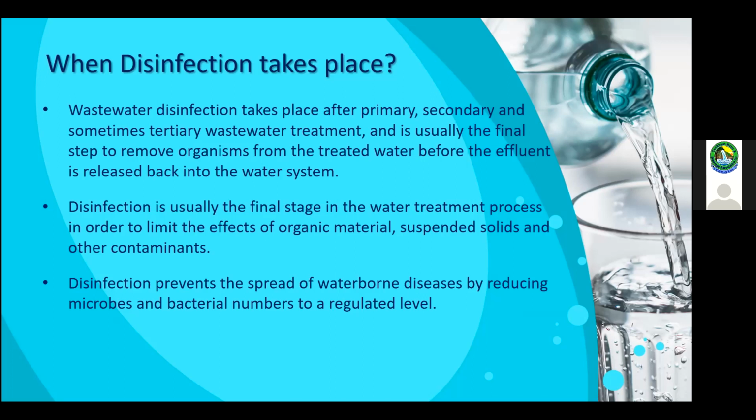It's just a slight bit different here in that you disinfect before the water goes into your distribution system or your storage system. And this is because you need to limit the effects of any residual organic matter, suspended solids, or other contaminants remaining in your water after your treatment process.